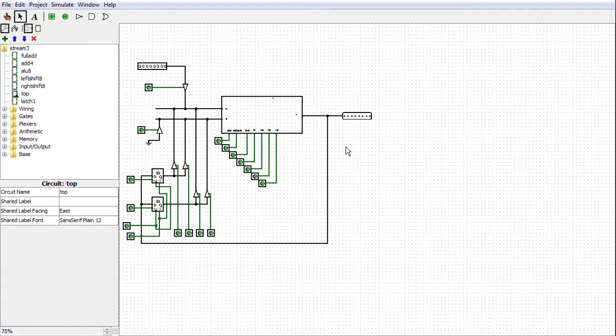Sounds good. So is RAM going to work similar to your registers? Yeah, basically, all we're going to do is put a bunch of registers in there, and we're going to have them addressable by some address lines. So we'll be able to select which register you want to read or write to. So what we'll do is, let me think here.